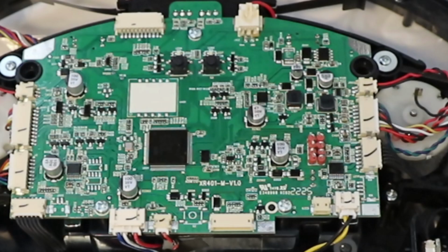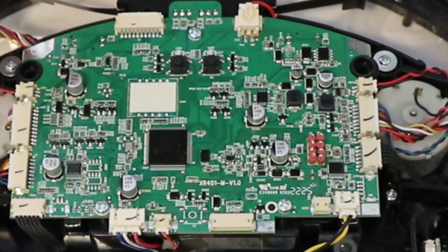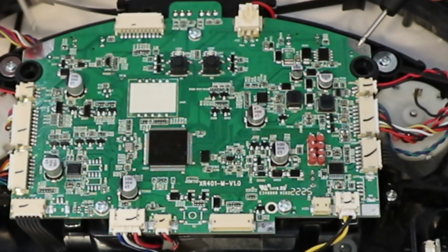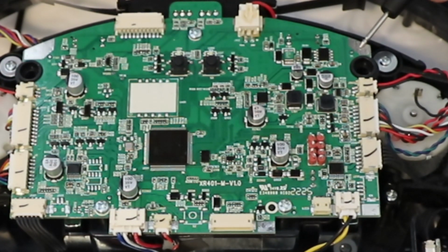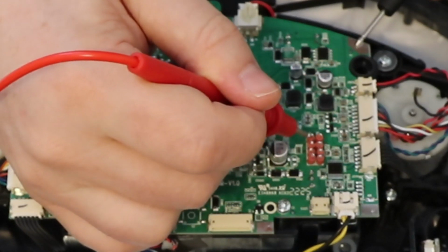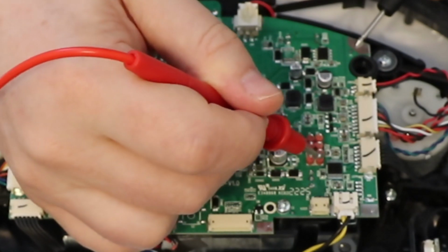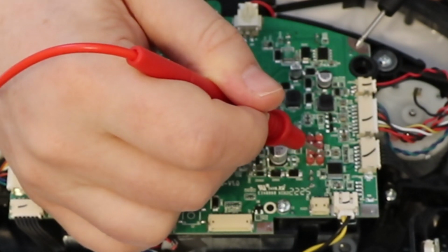The next thing we have to do is figure out what the pin out of these jumpers is. I'm guessing it's one is ground, one is power, one is transmit, and one is receive. So let's first try to identify ground. Right now there's no battery in the device. This is probably ground here, this metal thing, and it seems to be connected to the other metal thing, so I'm pretty sure this is ground. So if we test these pins, okay, that one is ground. That one's ground also.